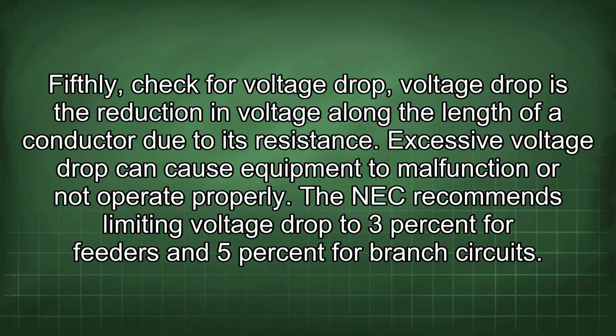Voltage drop is the reduction in voltage along the length of a conductor due to its resistance. Excessive voltage drop can cause equipment to malfunction or not operate properly. The NEC recommends limiting voltage drop to 3% for feeders and 5% for branch circuits.